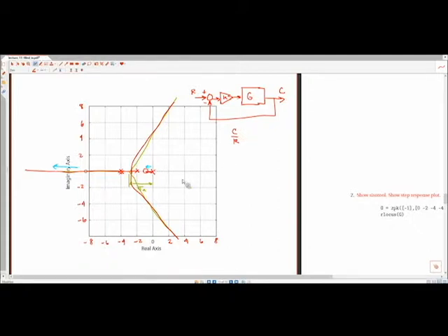Okay. So the root locus here shows us all the potential values of those closed loop poles, and we're saying that as k increases, the closed loop pole along this branch is going to go, and it's actually going to cancel this 0. So the effect of this pole really close to the origin is going to become nullified.